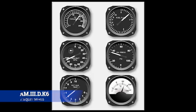When you start looking at jets, for instance, your rotational speed, your N1 on the Learjet, will directly correspond to an NG, which is the rotational speed of the turbine on the back, which will then produce a certain amount of torque. So it becomes the primary power output indicator that's delivered to the propeller or the shaft, helping assess the engine performance and efficiency.